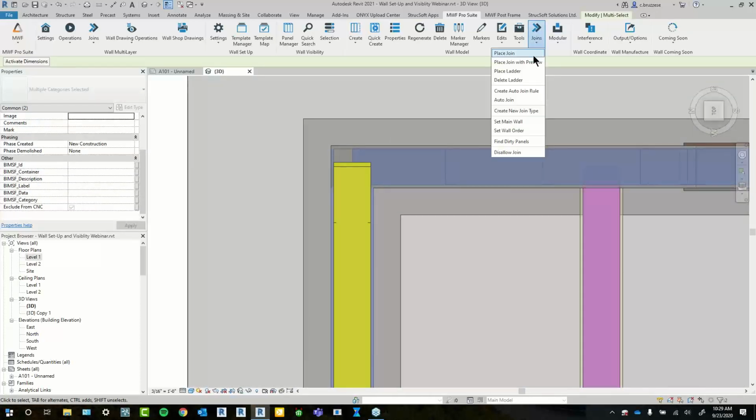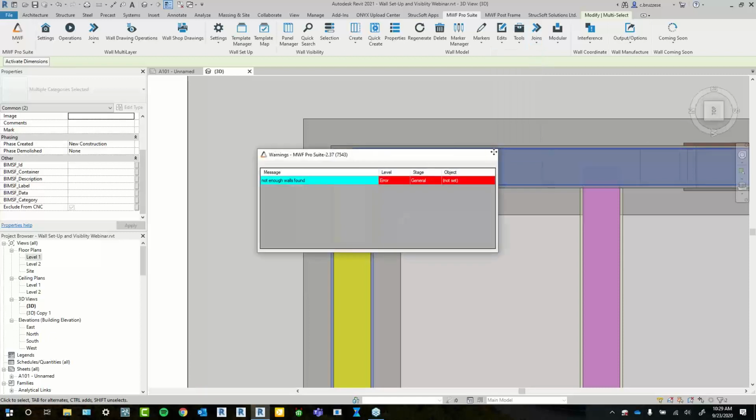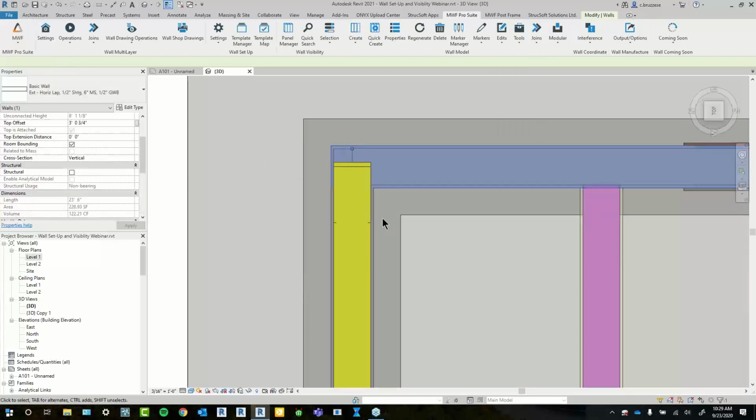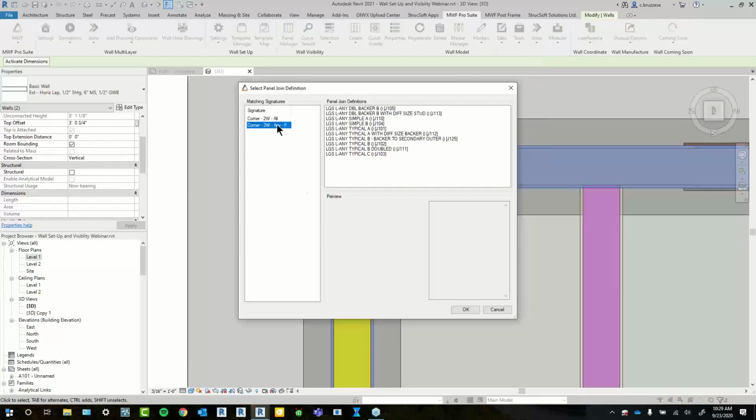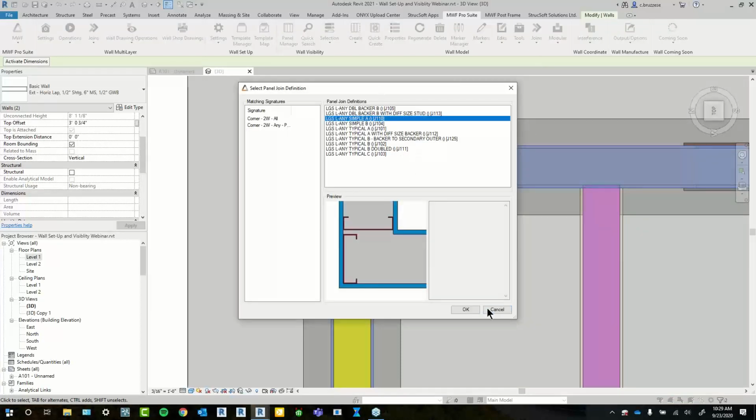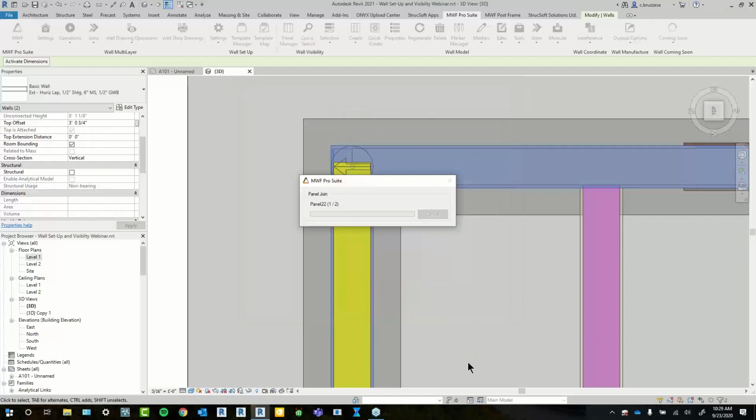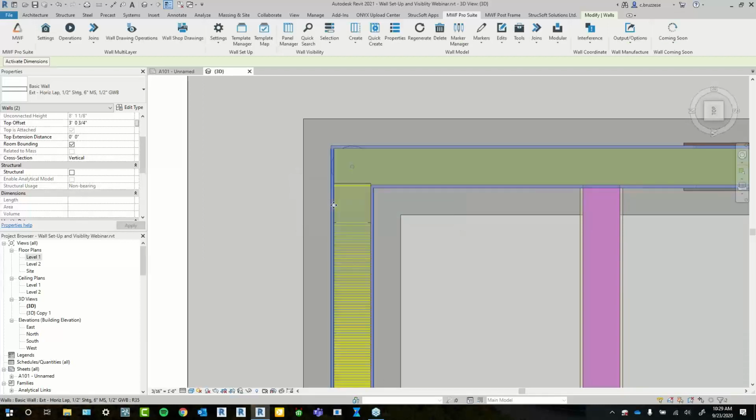So when I go ahead and actually join these together, let me grab the walls. Just give it an easy configuration. Instead of taking the sloping wall by default, it's taking the longer of the two, and the join arrow is going to reflect that.